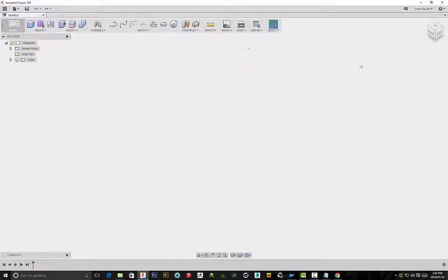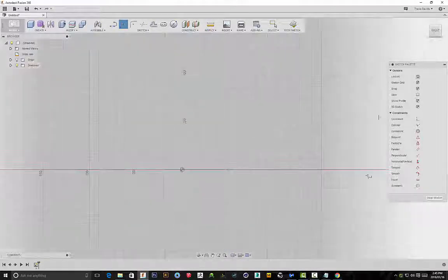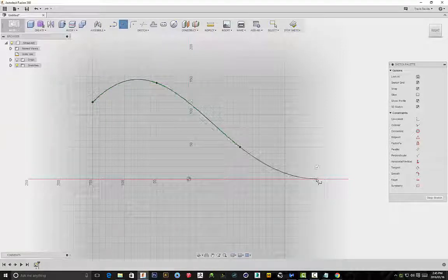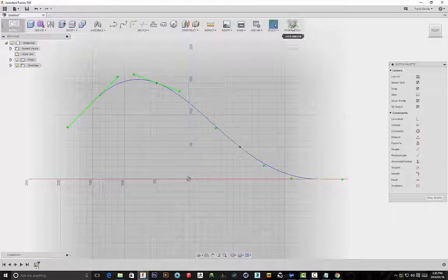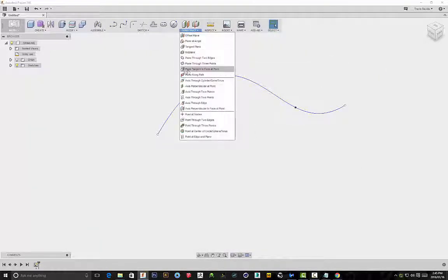And I'm going to show you another operation with lofting. So let's create a spline on this plane. Let's give it some curves. So let's start over here. Right now, just like what we did earlier, okay, wait, let me just click on stop sketch. Earlier we basically constructed a plane along a path.